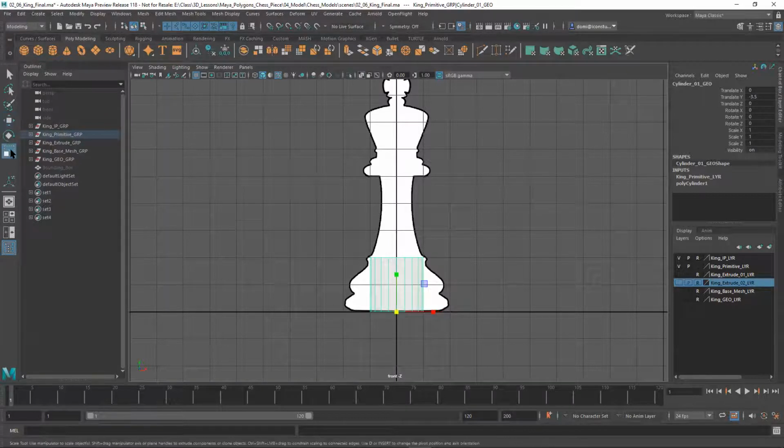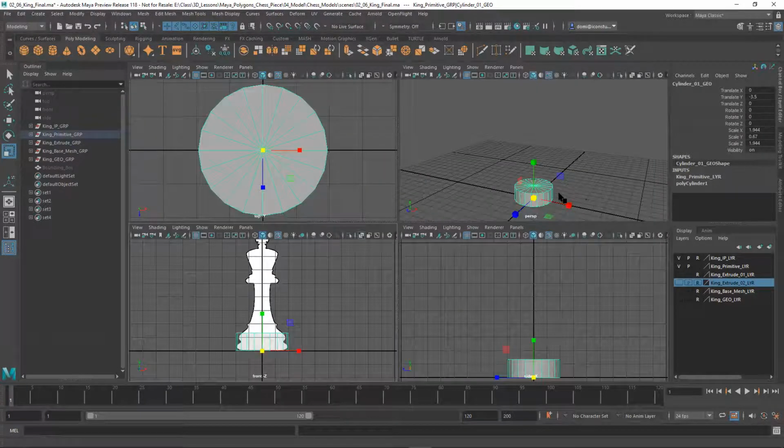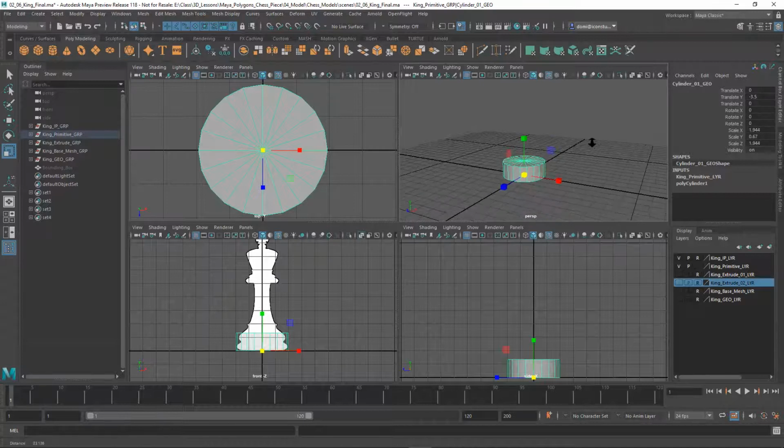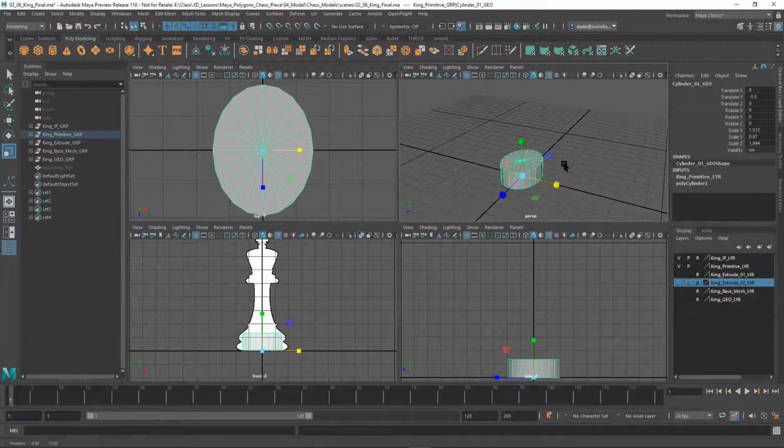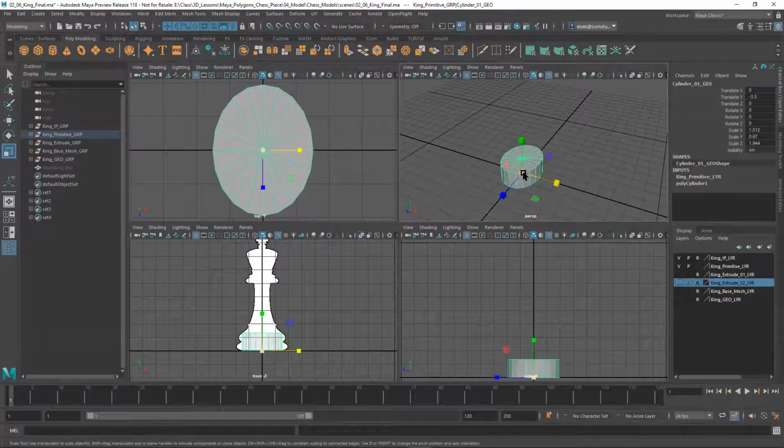Okay, so I'm going to go to scale, and I'm going to scale it down. So I'm going to basically get it to this level here. And I'm going to scale it up again because I want to get the full max to the extent of that edge there. Now the reason I'm using the global tool here is because if I just hit on that red thing, it's like, oh, let me scale it in over there. You'll see what's happening is it's getting ovular here. So you definitely want to be doing a global scaling in this view. I mean, in this circumstance, okay?